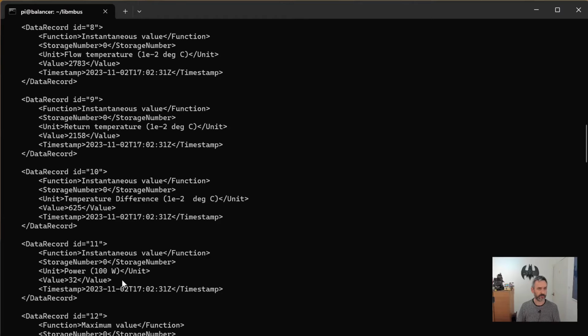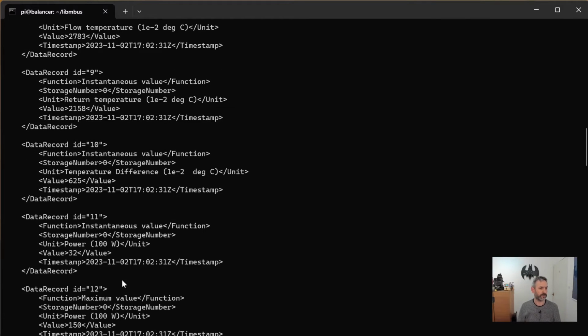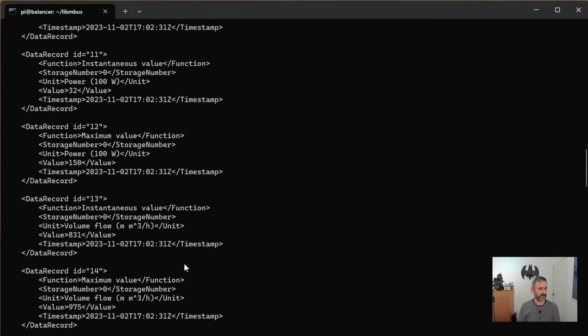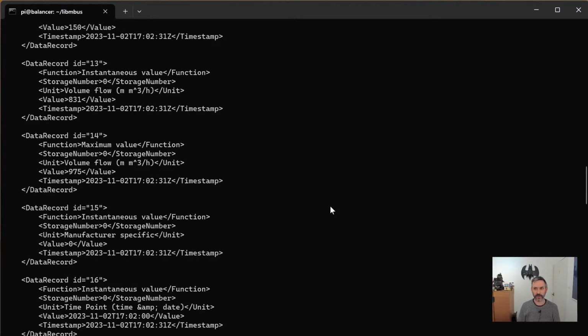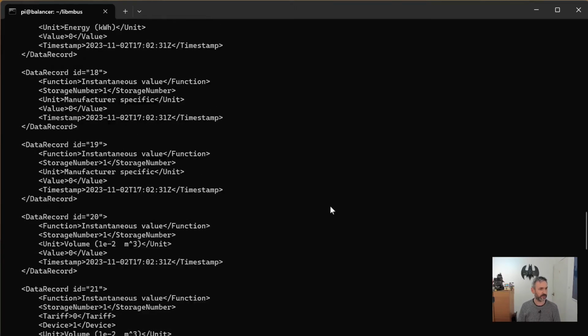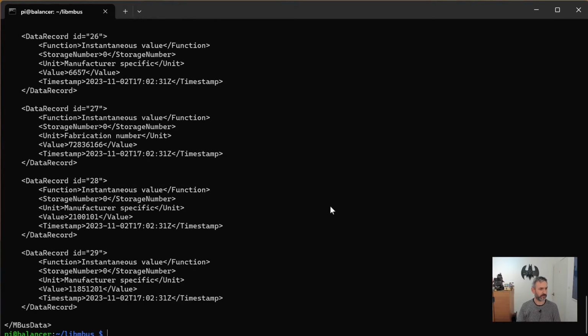I think it's a 30 kilowatt boiler. So 15%, it would be closer to 4. Yeah, so I'd expect that to be maybe 45. But I guess as the water is running, it won't have the heat coming back yet to give us an accurate figure. So we'll clear the screen.